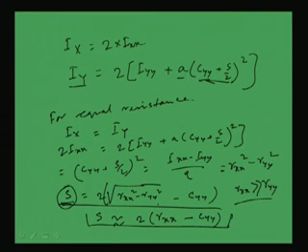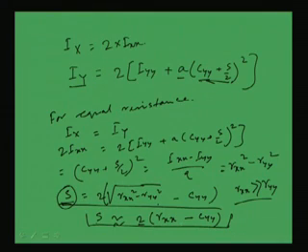What is the final expression? The spacing of the channel sections placed back to back will be approximately 2 into (Rxx minus Cyy). If we make the spacing from this equation, then Rxx will become Ryy, which means the column or compression member will give equivalent resistance from both directions. That means we are making use of the material in an optimum, economic way, so that maximum strength is available for that section.